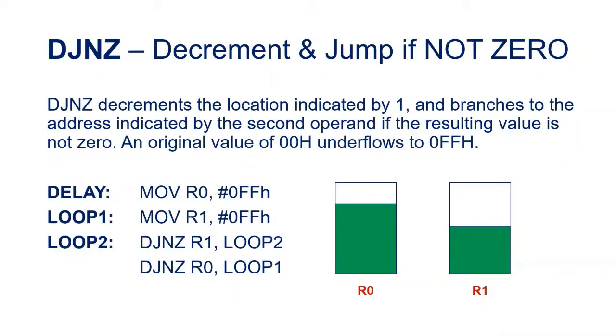Next is DJNZ, or yung tinatawag nating decrement and jump if not 0. Kung titignan natin, this is another variation of jump command, pero this time, the DJNZ is a conditional jump instruction. So pag sinabi nating conditional jump, meron tayong isa-satisfy na condition para i-execute niya yung jump command. Ulitin natin, decrement and jump if not 0. Ibig sabihin, i-decrement niya yung particular value and then mag-execute siya ng jump if yung value na dinecrement niya ay hindi pa 0.